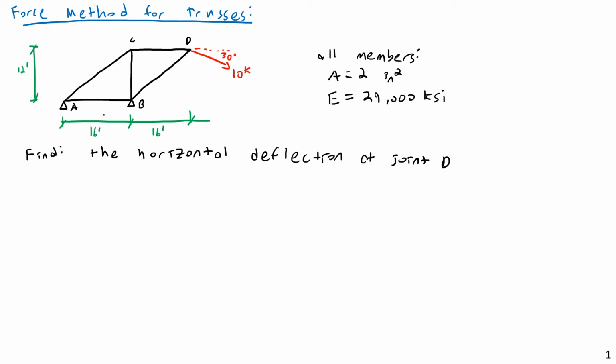We have already looked at things like this previously in the semester. We saw this kind of thing when we looked at the method of virtual work applied to trusses. So at first it seems relatively straightforward. However, take a look at our reactions here. We have not 3 reactions but 4.